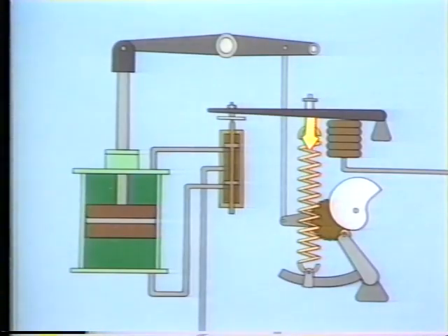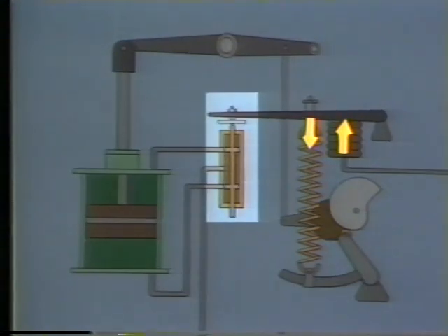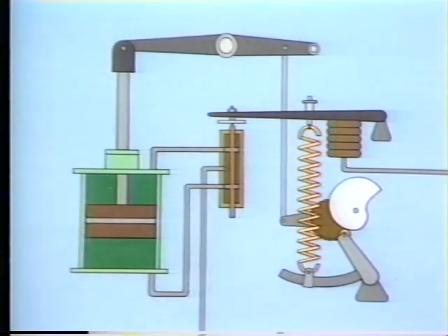This downward force on the balance beam counters the upward force in the bellows. When the downward force balances the upward force, the pilot valve closes so that no more air enters or leaves the actuator. This stops the piston from moving and holds it in position until the controller sends a new signal to the positioner.